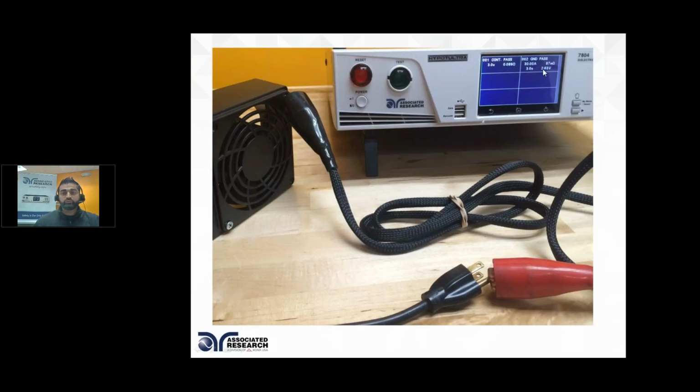You can also see the voltage drop. The new testers allow us to display this parameter, the voltage drop. So 2.83 volts were dropped across the ground circuit. Some standards do require a ground circuit voltage drop, and the newer instruments are able to tell you right off the screen how much voltage was dropped, instead of you having to calculate the voltage.